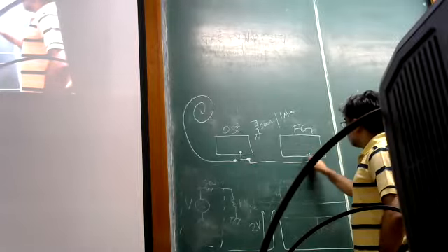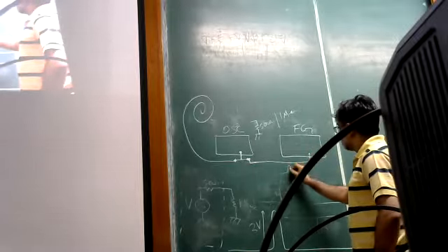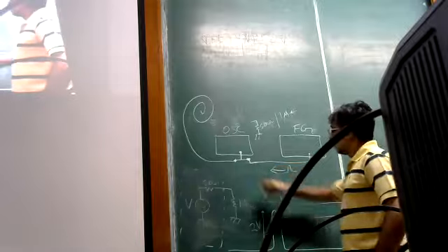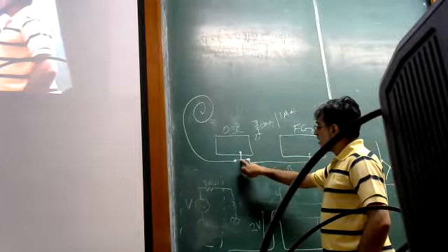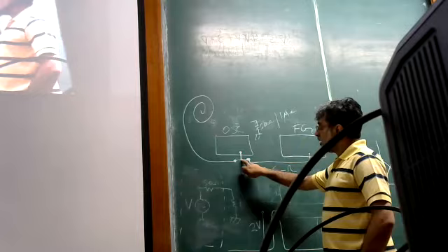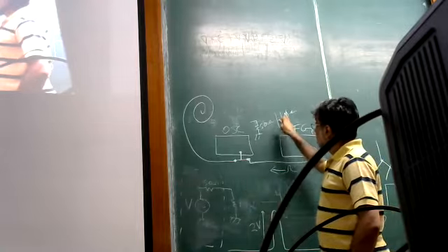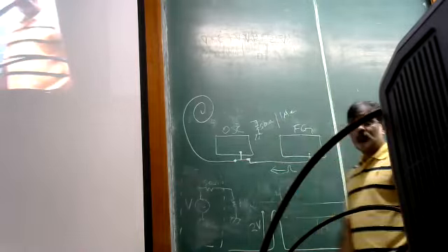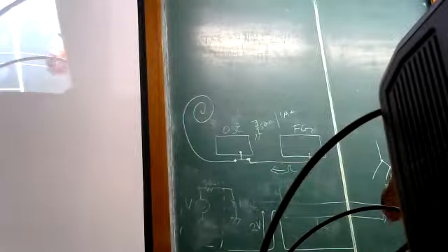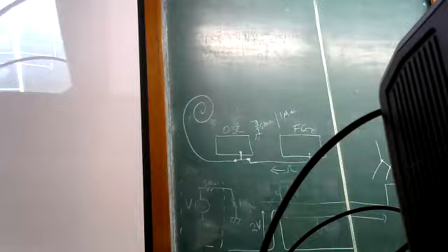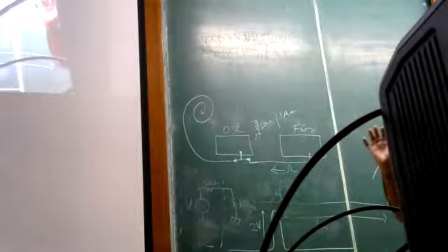So this signal here is going this way. Now it encounters this T junction, but the oscilloscope is set to 1 mega ohm input impedance. Let me give you a hint. That means that we can actually forget about the oscilloscope as being part of the circuit.